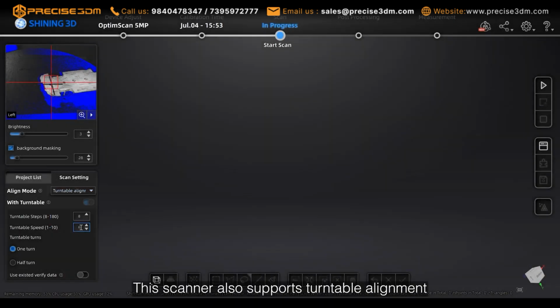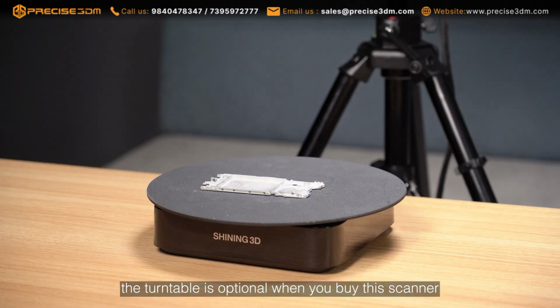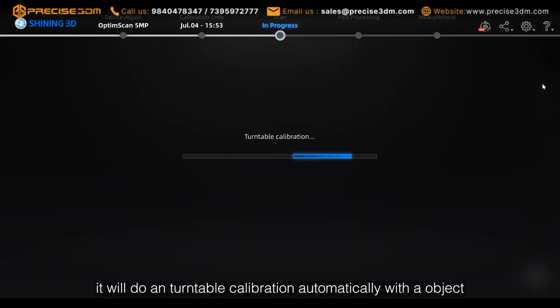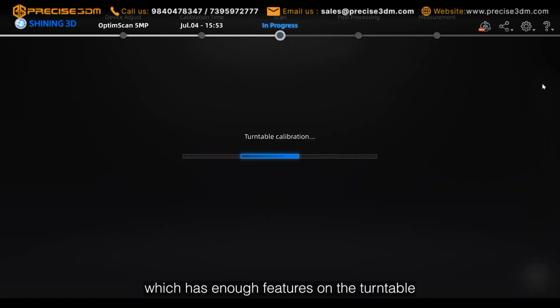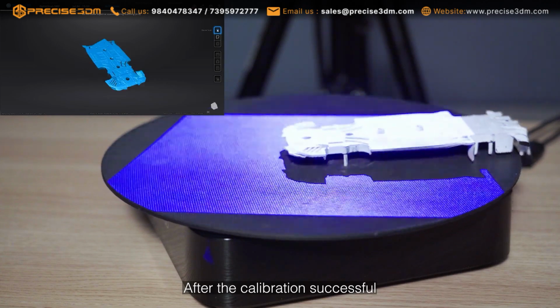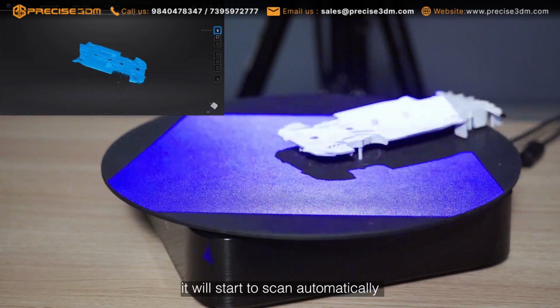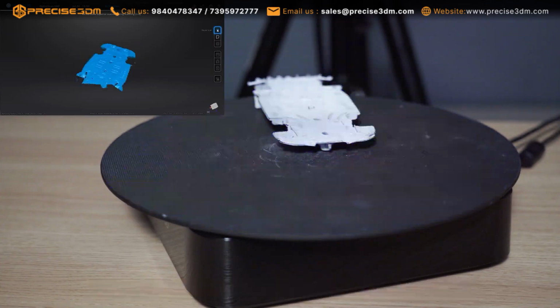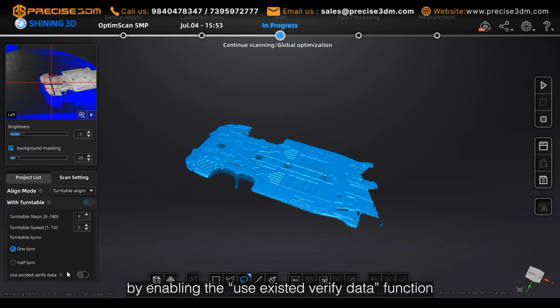This scanner also supports turntable alignment. The turntable is optional when you buy the scanner. Before the actual scanning, it will do a turntable calibration automatically. With the object which has enough features on turntable and within its scanning range, after the calibration is successful, it will start to scan automatically, and you can use the calibration data of the turntable next time by enabling the use exist verified data function, as long as the relative position between the turntable and the scanner does not change.